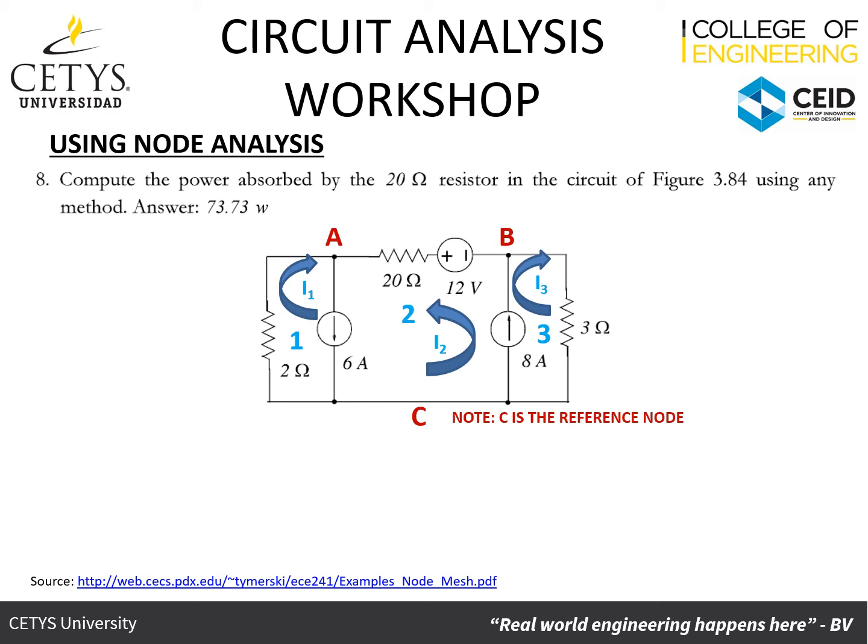So now we've identified the relationships using Kirchhoff's current law and Kirchhoff's voltage law and doing a node analysis. And so from mesh 2, we had this expression here, which was VB minus VA equals minus 12 volts plus 20 I2. And what we're going to do there is represent that equation with regards to I2.